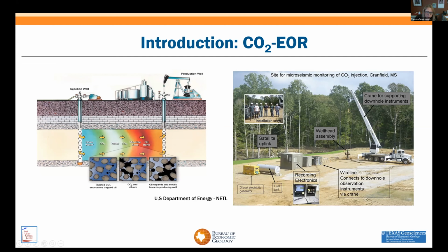Very commonly in the Permian Basin it is injected alternatively with water, because the CO2, even though it is a gas and is injected in supercritical state, and so in supercritical state it behaves more like a liquid than it behaves like a gas, but it's still very, very mobile, and it tends to get ahead of anything and form fingers and break through early to a producing well.